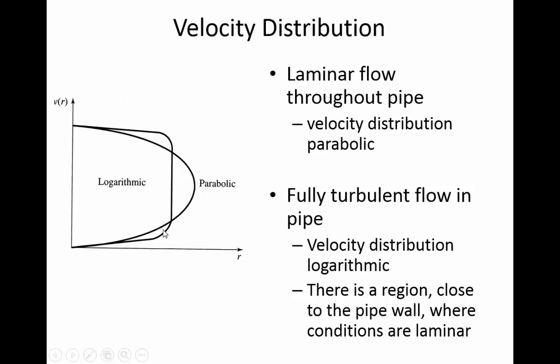When you have turbulent flow, on average, it will have this kind of a profile where this looks flat, but at any given second, if we took a picture of the flow field right now, maybe it looks like this. And then a few seconds later, if you take a picture of the flow field, it might be in a completely different spot.